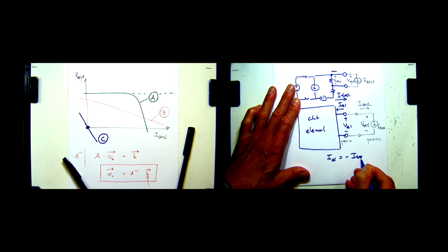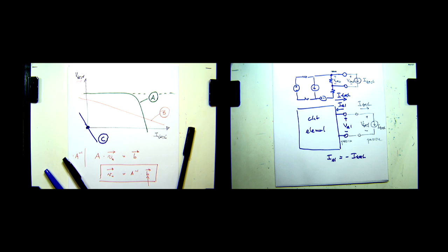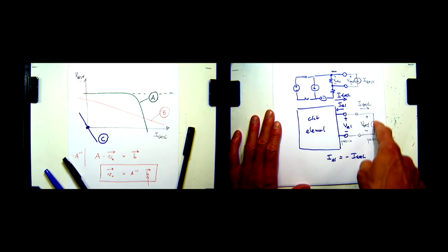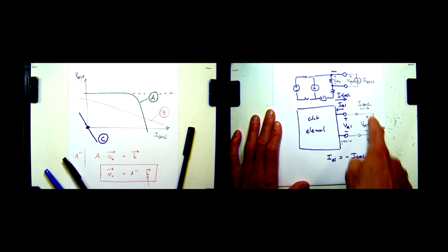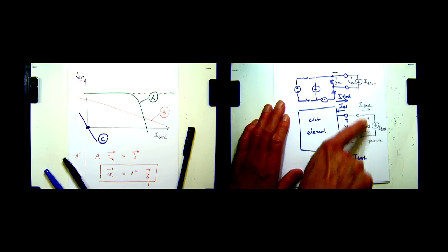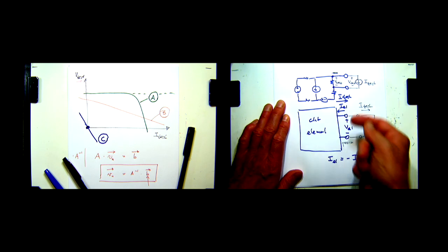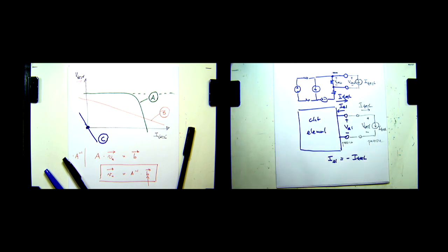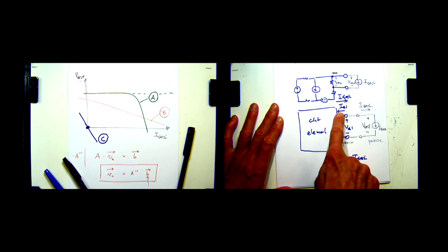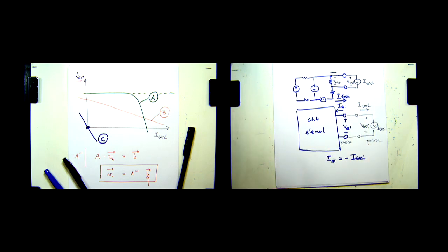I mean, this is simple geometry. You define the voltage from top to bottom, right? And then the current also flows from top to bottom. Well, but then this current, to also be passive sign convention, needs to go the other direction. So be careful about that, right? If you define multiple currents, then you may end up with non-passive sign convention. It's called active sign convention if you combine them in different ways.